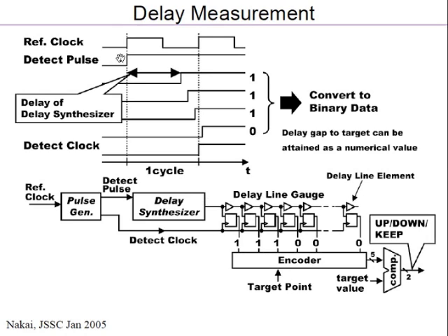What they do is the following: they launch the pulse using one of the edges of the clock. Just ignore some of these other things here. The idea is the following: at the rising edge of the clock, you launch an edge out here. After some delay, the edge comes here, and this edge propagates through this chain of buffers. At the output, you have flops. And at the next edge of the clock, you trigger these flops to capture the state of the nodes here.